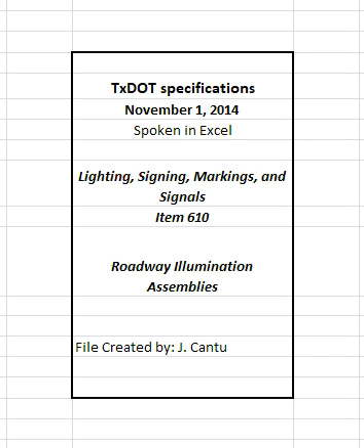3. Construction. Perform work in accordance with the details shown on the plans and the requirements of this item. Permanently mark roadway illumination pole base plates, at a visible location when erected, with the fabrication plant's insignia or trademark. Sample fixtures for testing in accordance with TEX 1110T. Use established industry and utility safety practices when installing, relocating, or removing poles or luminaires located near overhead or underground utilities. Consult with the appropriate utility company before beginning work.